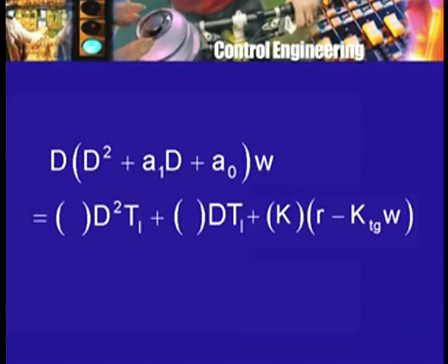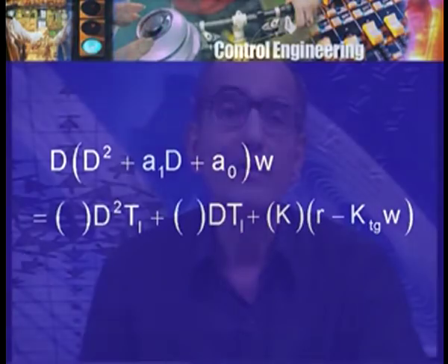Therefore, there will be three roots that we will have to think of, and the transient response will depend on the nature of the three roots. For a cubic also there is a formula, but it is too tedious. So, once again it is better to use an approach like the root locus method to investigate where the roots of a polynomial lie as a particular parameter varies.